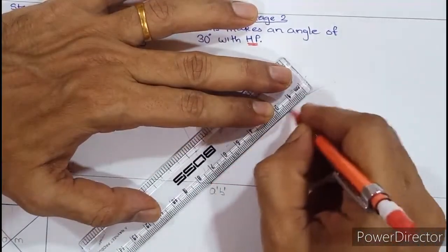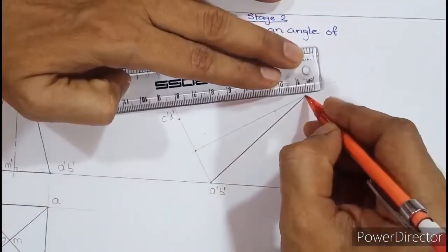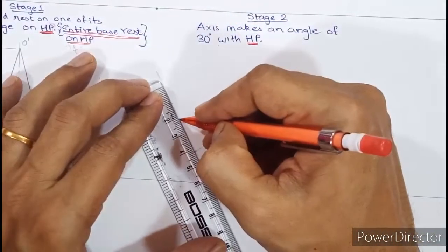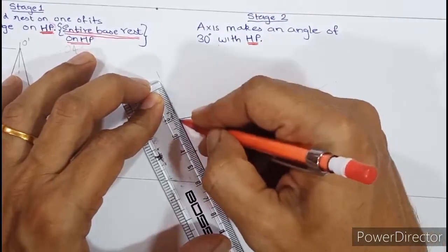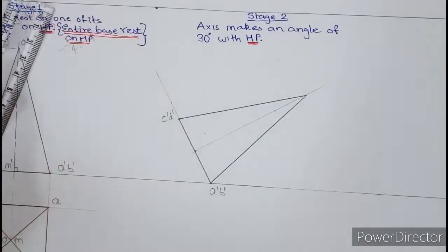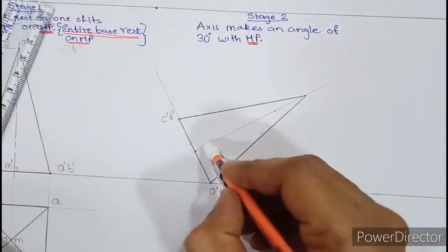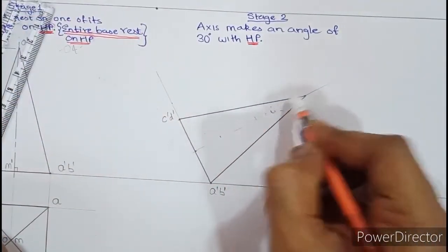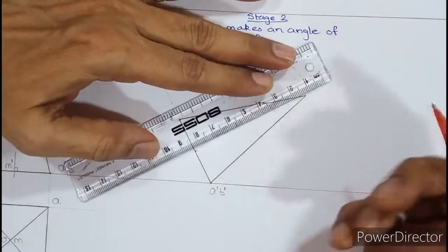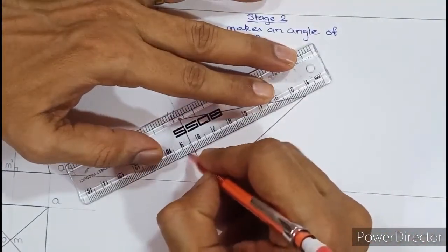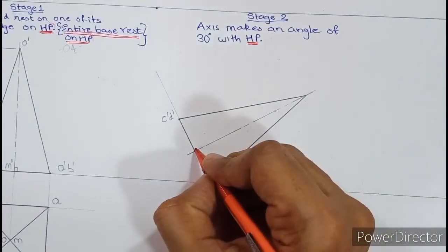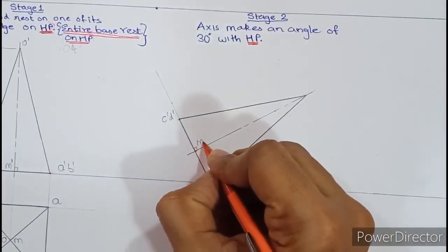So you need to reproduce the same diagram. That means you're just changing the orientation of the square, that's it. You're not doing anything else. In the center, you need to replace this by a medium dark axis line. Okay, so this line has to be replaced by a medium dark axis line. It should not be a continuous line. So align the scale and we'll draw big dash, small dash, medium dark. Show the sign of perpendicularity and we can write M dash inside.